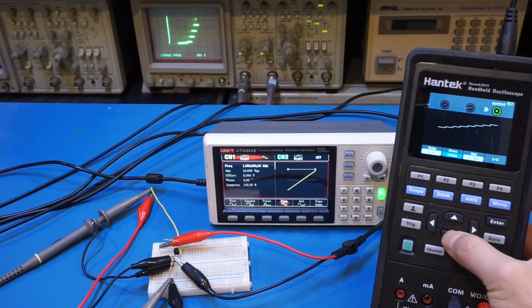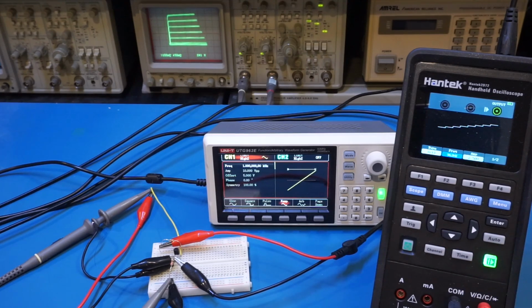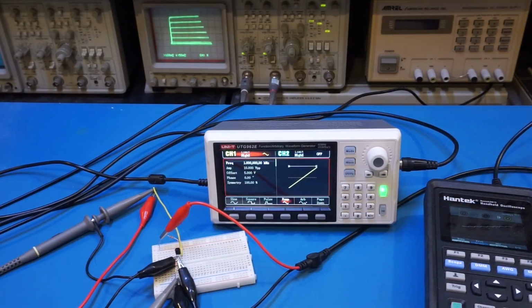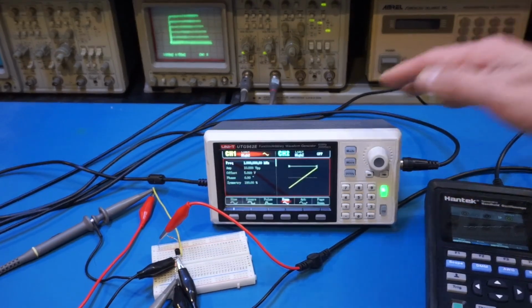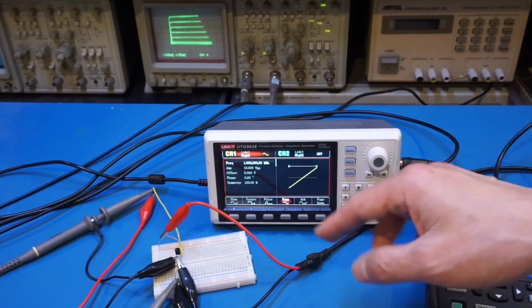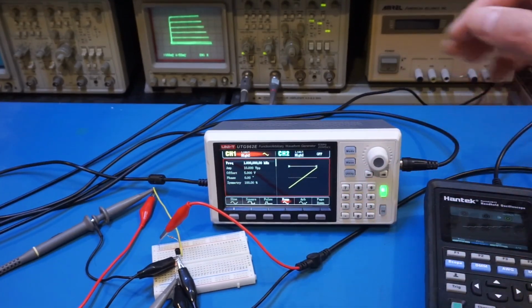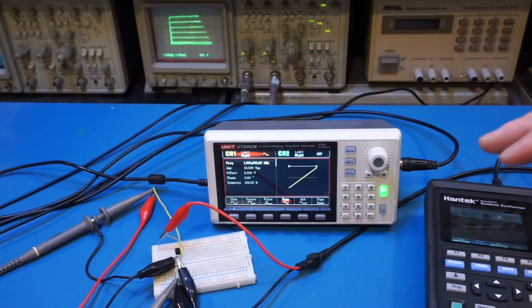So we will make sure that these two frequencies are as far apart as possible and not integer multiples of each other. One of the limitations of using a signal generator to sweep the emitter and collector voltage is that the output from the signal generator is generally very limited.